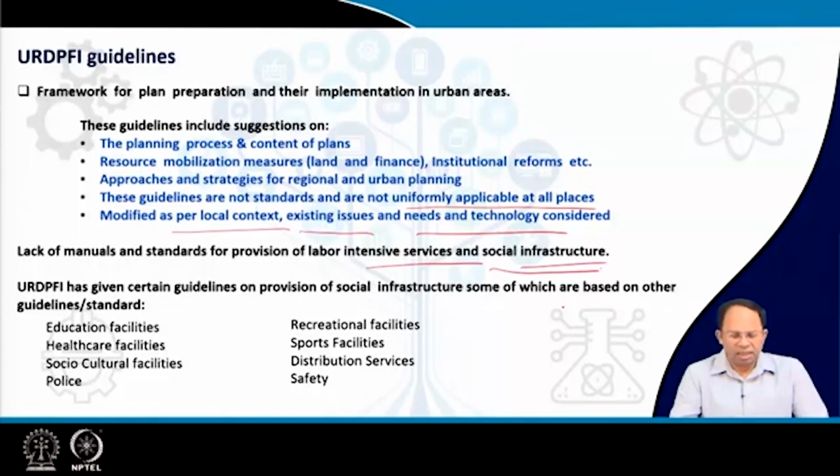And what are these guideline standards based on? These are in regard to provision of educational facilities in urban areas, provision of healthcare facilities in urban areas, socio-cultural facilities, police stations and other security or safety facilities which look into the safety of the urban population, like disaster response and so on, distribution services, gas distribution, food distribution and other kinds of distribution services, sports facilities, recreational facilities and so on. URDPFI guidelines do give some standards for this, but again these are very broad guidelines, and as per the context we have to modify them.